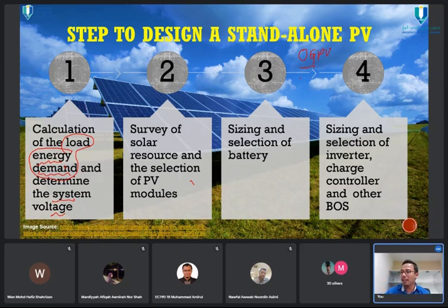That's critical. With depth of discharge, newbies just have the battery, calculate just like that, then install, and then, oh, not enough energy. The battery dies. Why? Maybe the battery is not good? No, it's not that the battery is not good. It's actually that our calculation is not good. That's the problem. So first of all, remember the load energy demand.